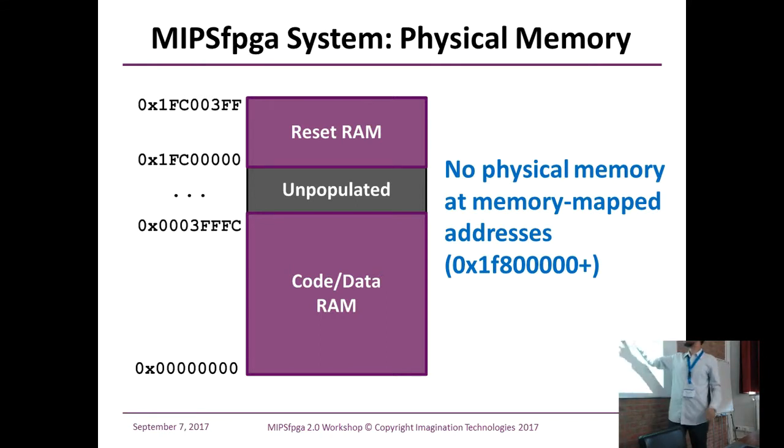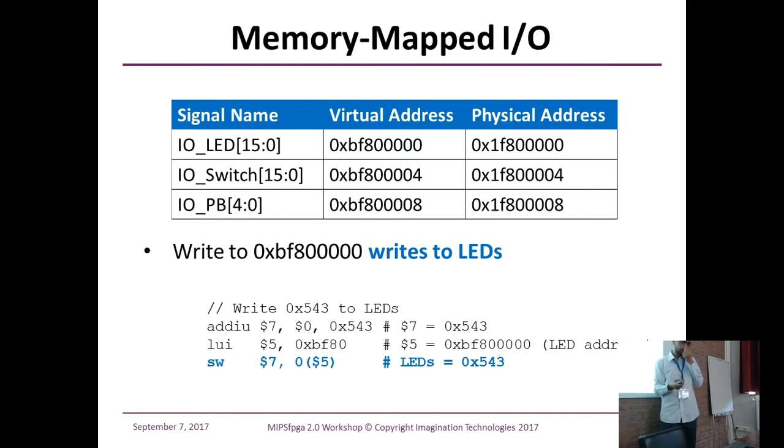There's no physical memory at this address location. So if you want to add your own peripheral, just find out where there's a gap in the memory map, add a few registers there, wire it on the AHB-Lite bus, and once you read or write to those registers, it should communicate with your peripheral. Okay. So this goes through the same thing with a bit of assembly.